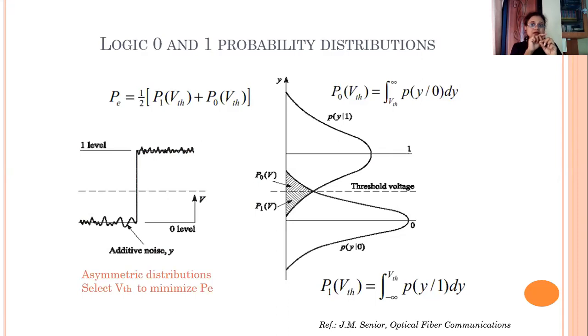So you can link this to the concept that if the bit is 1, in the modulated output a light pulse is present. The presence of a light pulse means what? Presence of photons, and this is linked to the statistical noise. So if bit 1 is transmitted, it is accompanied by the statistical noise because photons are present.